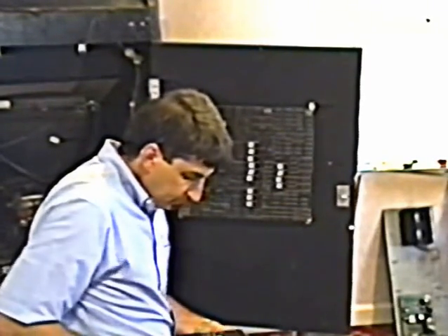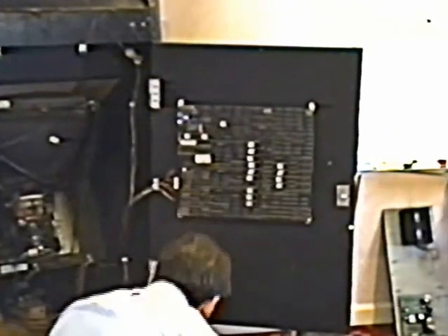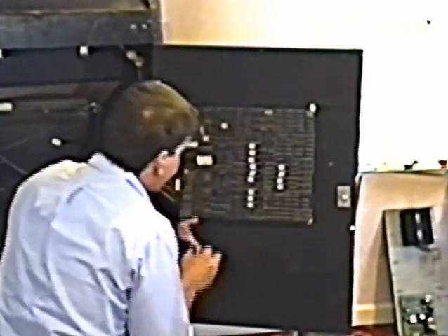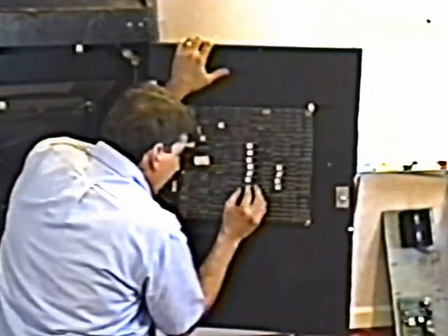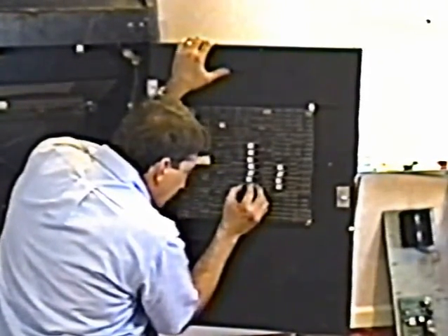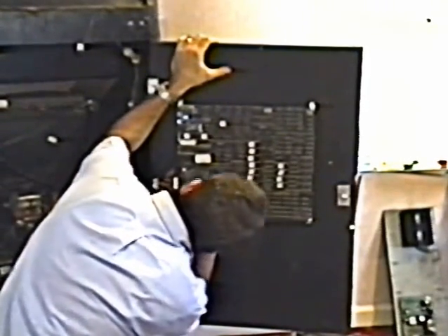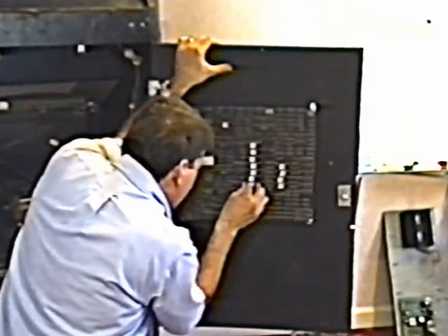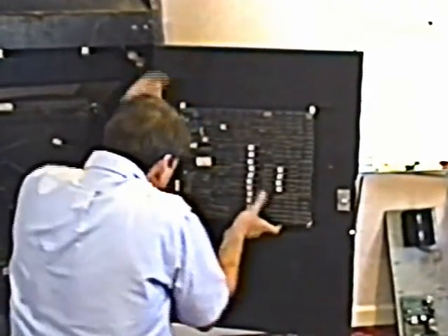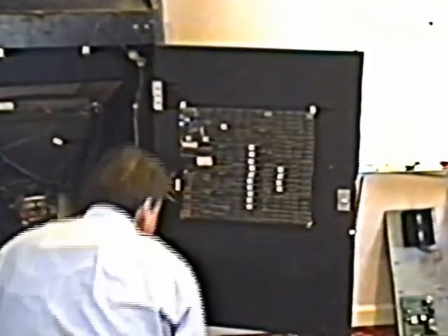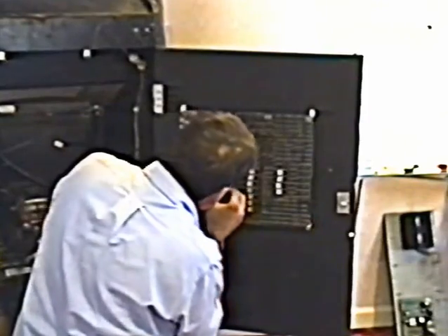So be really careful when you do it. Let me just put this chip back in here. Make sure the notch is going the right direction. What I usually do is put in one side partway, then put in the other side. Are they all lined up? I hope so. Well, it's not my game anyway, so it's not that big a deal. There we go. And let me just put the integrated circuit back in that I pulled out that actually caused the failure.